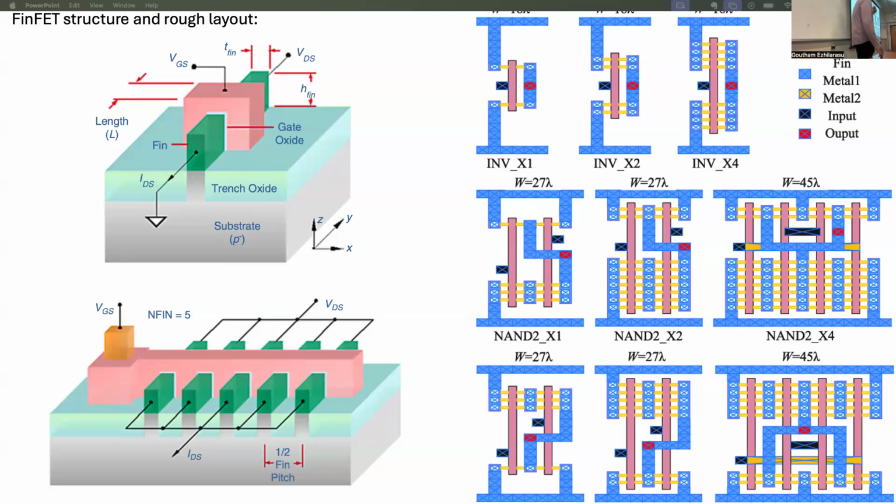It's like the source part of the PMOS. No, see this is the source and drain of the transistors, right? This is a metal line. So how do you go down? You have to go all the way down to the transistor, right? From the top, we're connecting VDD to that. Yeah, this is the VDD. So this is one metal line that carries VDD.